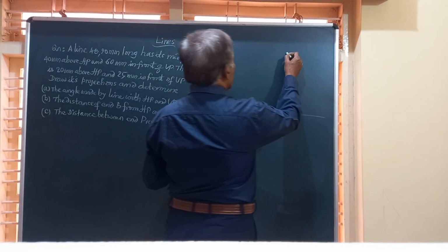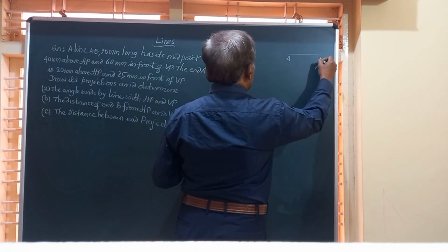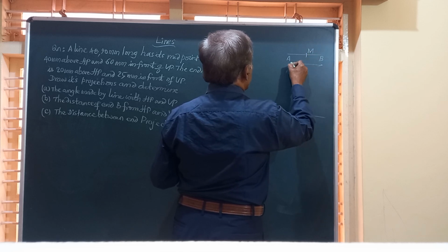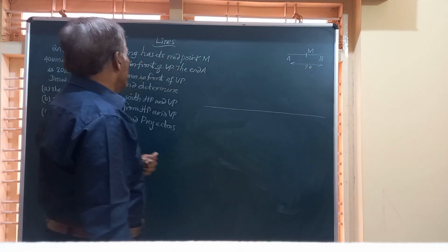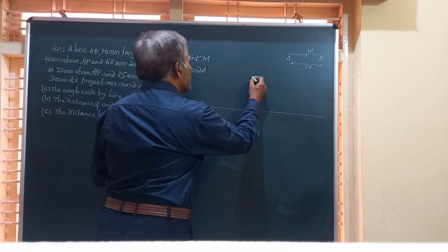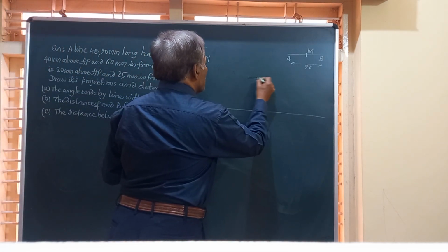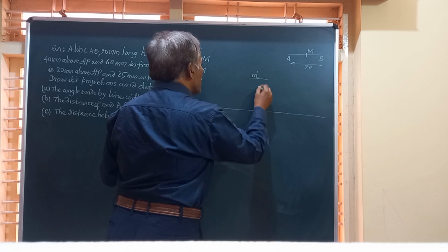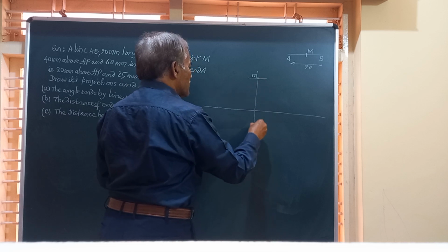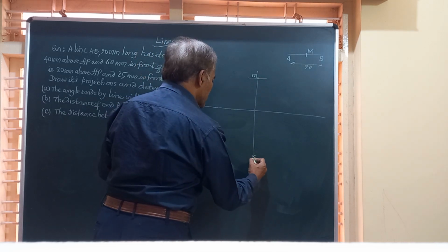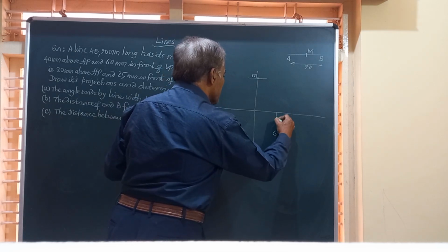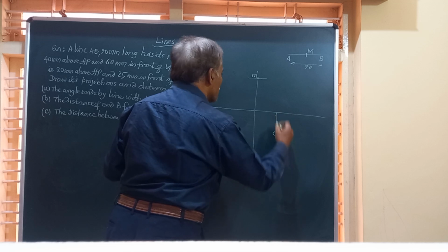So we will write a line here represented as AB and there is a midpoint here. The total length of this line from A to B is 90 mm. The midpoint is 40 mm above HP. Friends, I can simply mark here the point M dash, the front view, at a height of 40 mm. This is 40 mm above this. Extend that line downwards and get this point M, the top view of that, at a distance of 60 millimeter from VP.